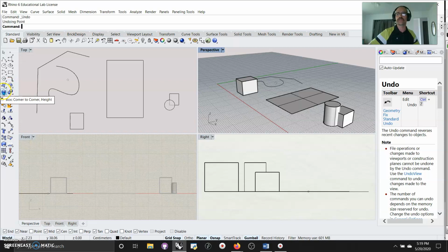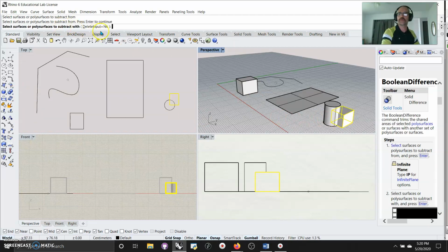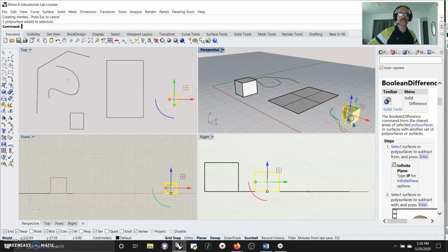do you have surface tools that you can use, you have box and then you have box tools. So if I went in here and I right-clicked and I chose a Boolean difference, I could select my first object, hit enter, always reading your command line in full detail, what's to be minus from it, and now you have a very interesting B-rep.